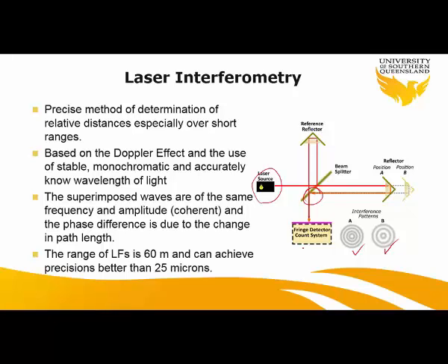And there is a fringe detector. We know about the fringe from satellite geodesy; it basically works based on monochromatic wavelength detection, and from the difference between the phases of the two returning signals, it creates a different pattern which gives you the change in the path length. So it's basically relative distance, it's not absolute. You change your position from A to B, and it gives you the relative movement of that target. To start off, you start from one position, and when you move, it gives you the relative distance to the first distance, or D0, that you had.